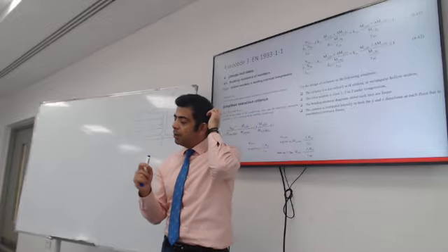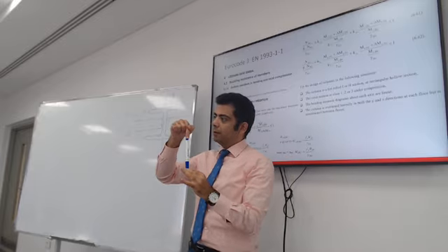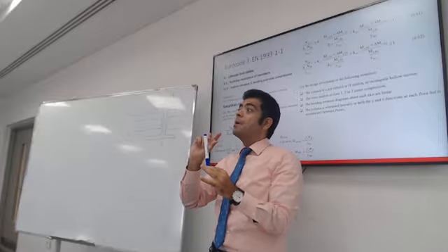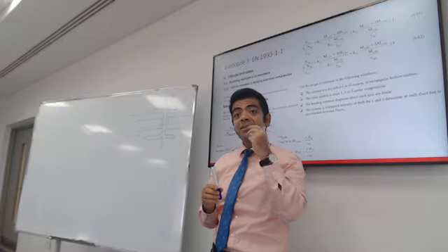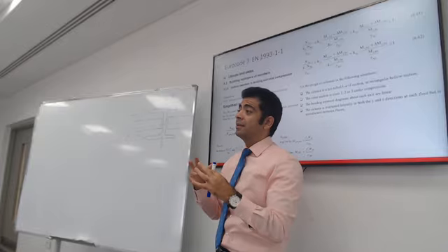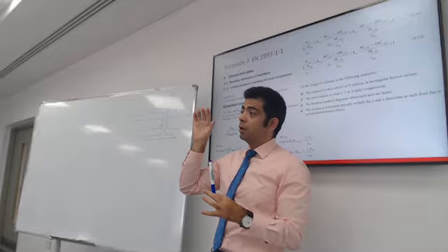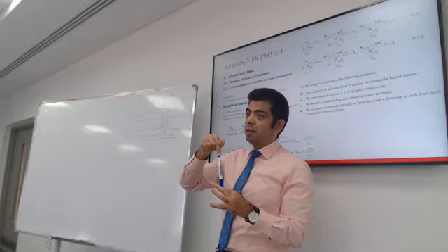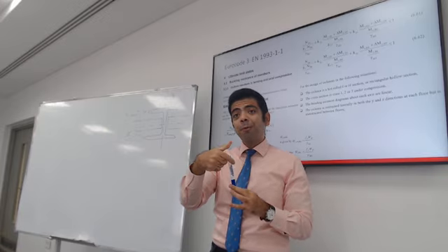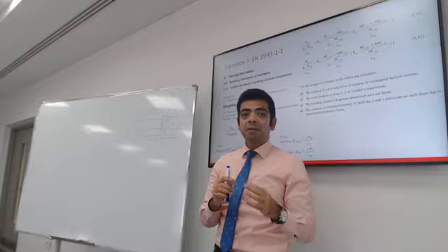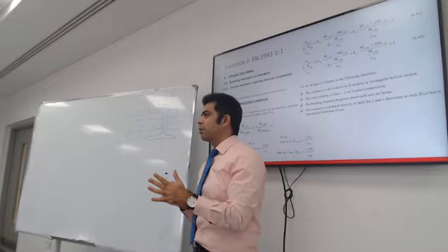So let's think about it for a second. How do you make sure that a column that has axial load, moment about X, and moment about Y doesn't fail? How do you design something that has these 3 straining actions acting at the same time? Can you develop the full axial capacity of the column and the full moment capacity about X and the full moment capacity about Y at the same time? Can you compare the loads to the maximum capacity in all directions?